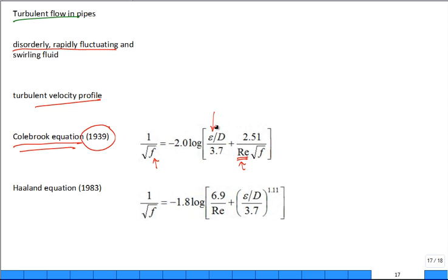And they have the roughness of the pipe, so that a lot of times they don't have smooth pipe. The pipe has some roughness, and they characterize that roughness, and they compare it to the diameter of the pipe. So this ratio is a roughness to the diameter of the pipe. The next slide will show you some typical values for roughness. If you have PVC pipe, like you buy it, a lot of water lines, it's very, very smooth. Roughness, you might as well just throw it out. 0. So small. If you have drawn copper tubing, we have a lot of water in PVC and a lot of water in drawn copper tubing. It's very smooth. Throw it out.